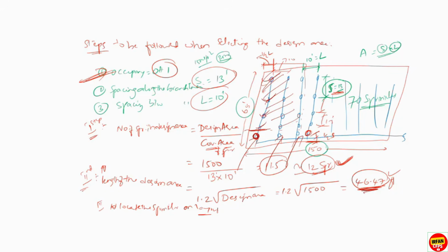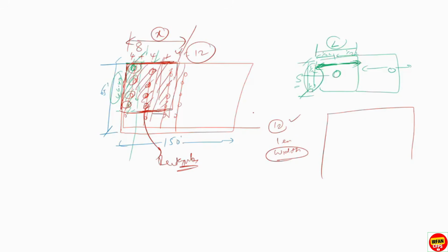But just remember, you select these 4 sprinklers and just extend this line. That's it. Whatever is coming in between, you just take those sprinklers. Most designers, if they don't know the requirement, will select, for example, 5 sprinklers, 1, 2, 3, 4, 5.